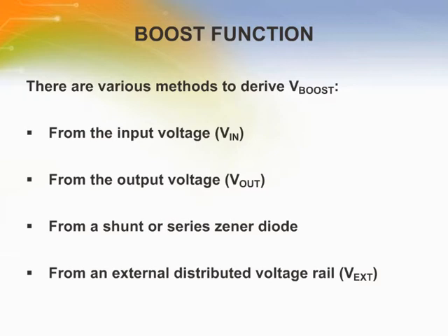When the LM3405 starts up, internal circuitry from VIN supplies a 20 milliamp current to the boost pin, flowing out of the boost pin into C3. This current charges C3 to a voltage sufficient to turn on the switch. The boost pin will continue to source current to C3 until the voltage at the feedback pin is greater than 123 millivolts.